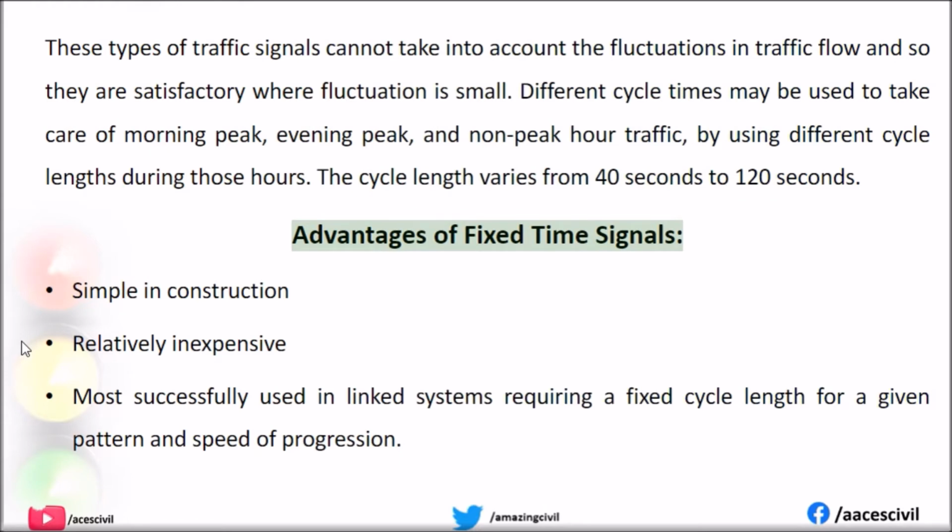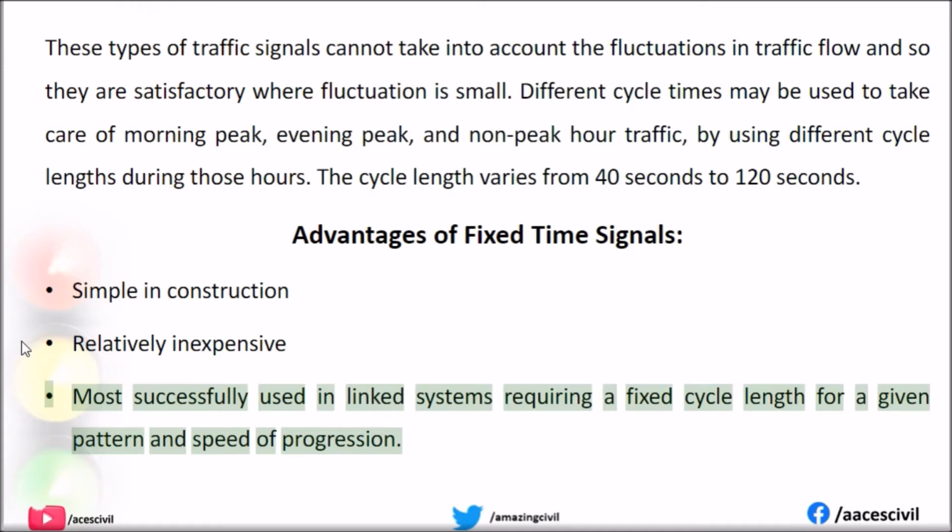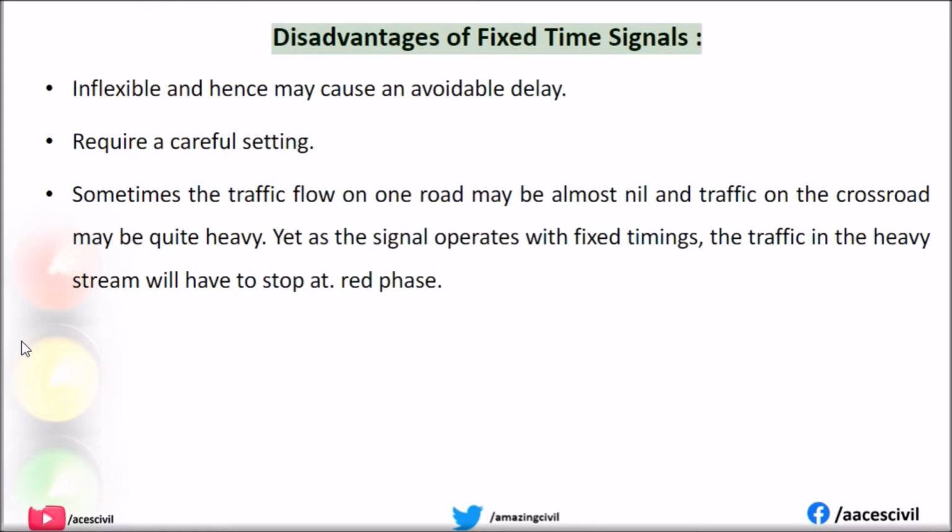Advantages of fixed-time signals. Simple in construction. Relatively inexpensive. Most successfully used in linked systems requiring a fixed cycle length for a given pattern and speed of progression. Disadvantages of fixed-time signals. Inflexible, and hence may cause avoidable delay. Require accurate fixed setting.